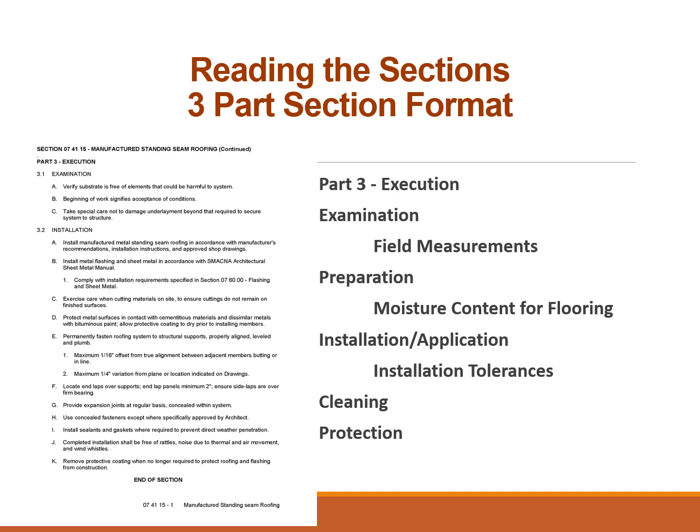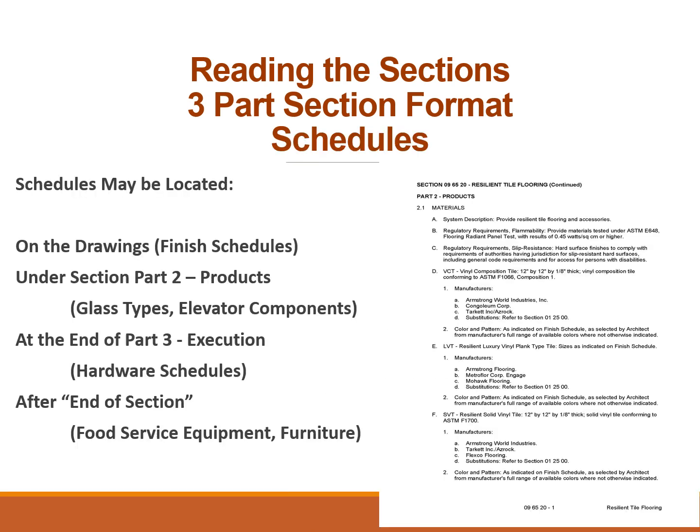Preparation, we want to know moisture content for flooring systems, and then basic installation application requirements. Other than saying that we want to follow the manufacturer's recommendations, here's where you can give them installation tolerances, how flat it has to be, or how far it can vary off of a straight edge over a 10-foot area. And then finally, cleaning requirements and protection. So that's the three-part format.